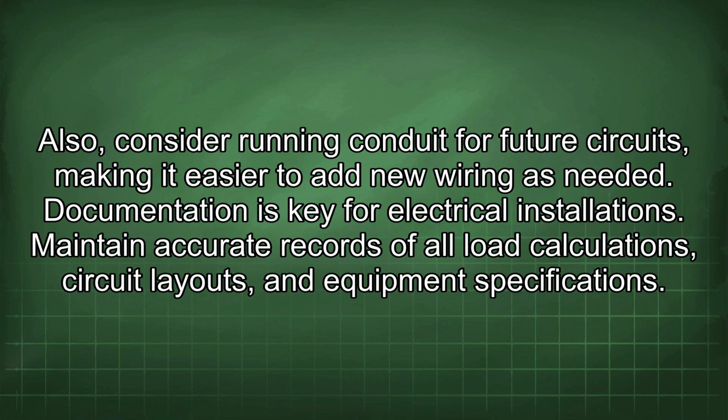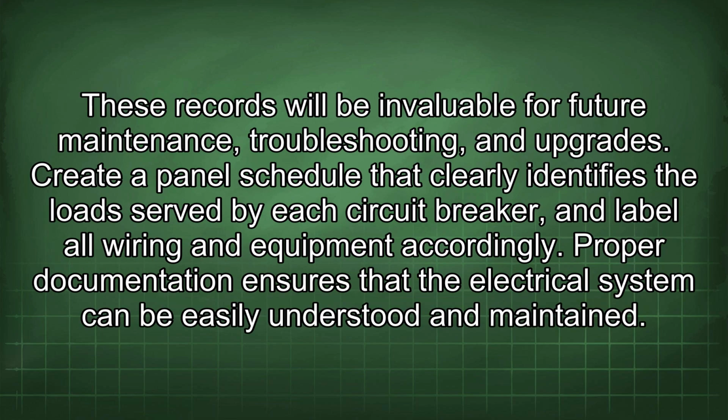Documentation is key for electrical installations. Maintain accurate records of all load calculations, circuit layouts, and equipment specifications. These records will be invaluable for future maintenance, troubleshooting, and upgrades. Create a panel schedule that clearly identifies the load served by each circuit breaker, and label all wiring and equipment accordingly. Proper documentation ensures that the electrical system can be easily understood and maintained.